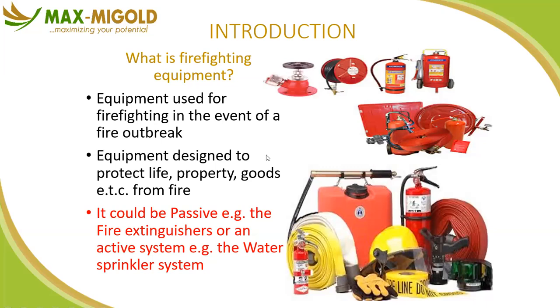All right. So for us within the building, we need to design safety into the building. So we need to have what we call safety in design, SID, where you ensure that even the building has factored in safety into it. So when I say safety now, it's not just about fire prevention, but also fire protection and fire evacuation. And in the best case scenario, even fire extinguishing, or should I say firefighting.